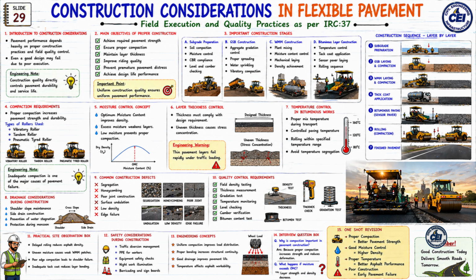Now let us look at the eighth topic. 8. Drainage considerations during construction. Drainage management is very important during the construction stage. Shoulder slope maintenance. Side drain construction. Prevention of water stagnation. Protection during monsoon. If there is water stagnation, so the layer strength starts reducing.